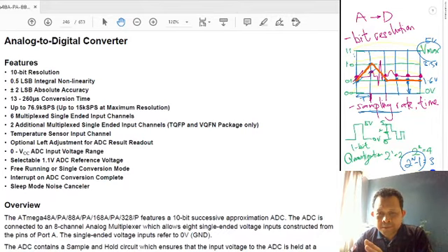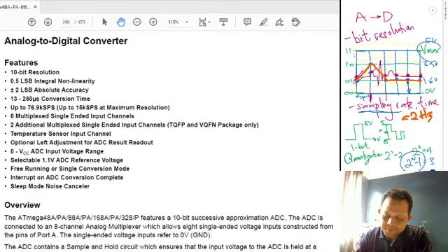So you can say that this system, with the spec of 2 bits resolution and a sampling rate of, let's assume, 2 hertz. 2 hertz means 2 samples per second, right? So the time interval is 0.5.